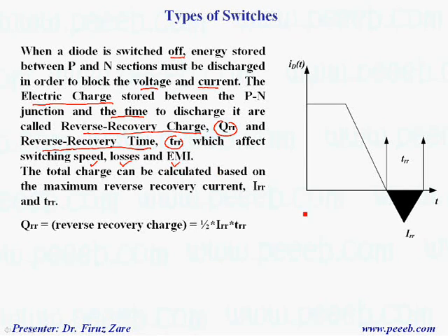So basically we can calculate this charge, which is QRR. If you look at this triangle, we can calculate this area, which defines the total charge.